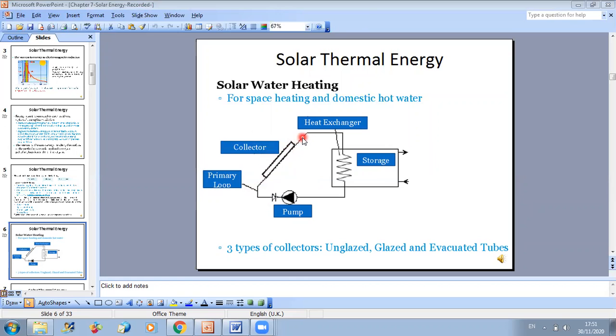And then to benefit from this heat, I will take the water into a heat exchanger. In the heat exchanger, I have two possibilities. If I don't need the solar energy now, I can use a certain medium to store energy by taking it from the circulating water. Or if I am in need of water that is cooled, for example, I can circulate in the heat exchanger another fluid, for example, domestic water that is needed in the house.